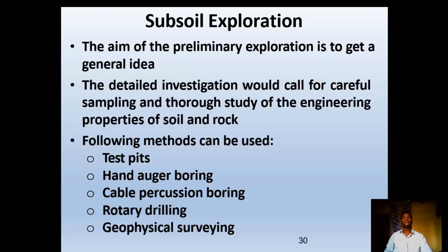Subsoil exploration. The aim of the preliminary exploration is to get a general idea. The detailed investigation would call for careful sampling and thorough study of the engineering properties of soil and rock. The following methods can be used: test pits, hand auger boring, cable percussion boring, rotary drilling, and geophysical survey.